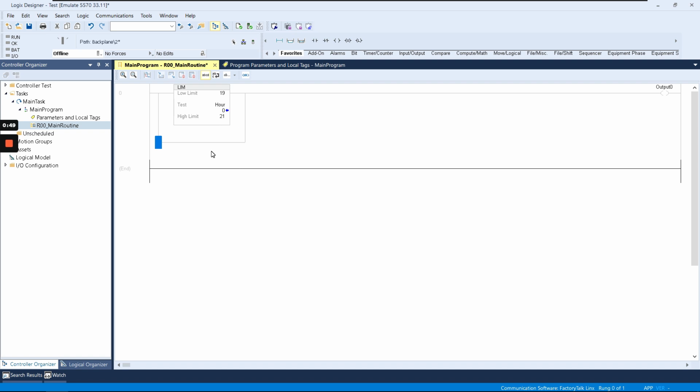So we have a limit, an instruction that we already saw for our smart house. But what was I trying to get to? So we compare our lower limit to our upper limit, and we compare it to our test in our memory, which in this case is a virtual memory, which I created, which is double integer. This is a physical memory, which is Boolean.